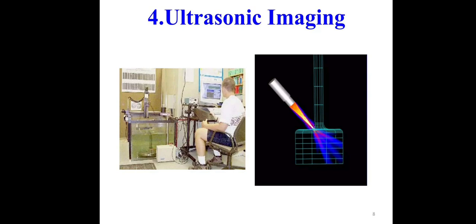In ultrasonic inspection, an ultrasonic beam travels through the testing object and internal defects such as cracks interrupt the beam and deflect back a portion of the ultrasonic energy. The amplitude of the energy reflected and the time required for return indicate the presence and locations of any flaws in the testing object.